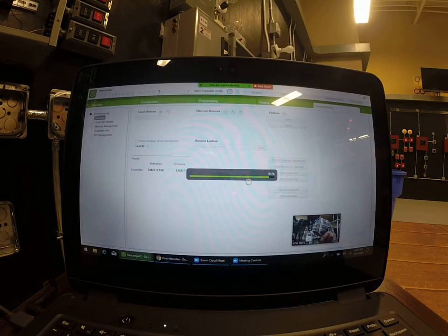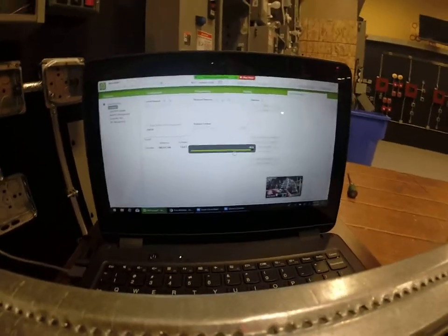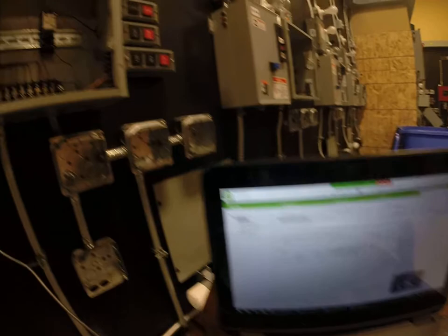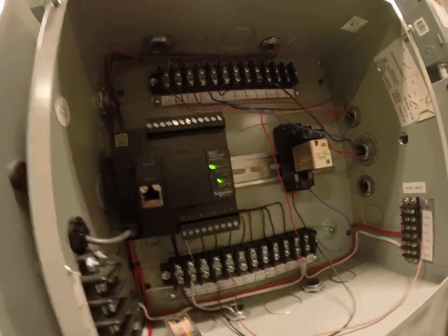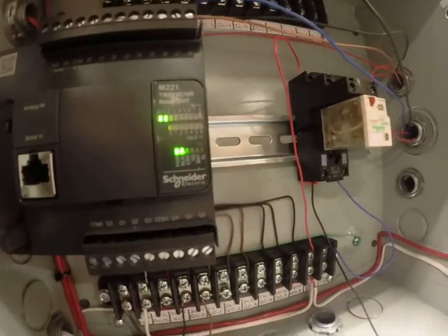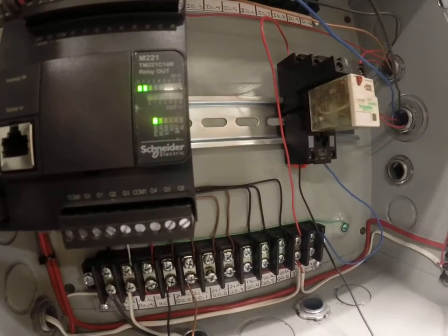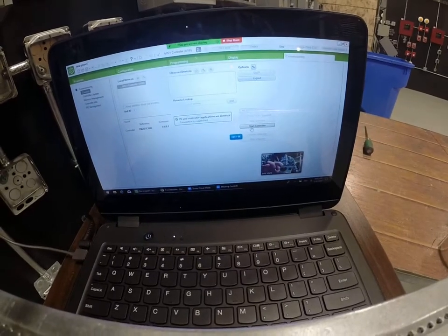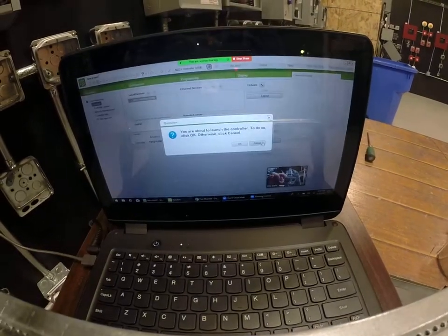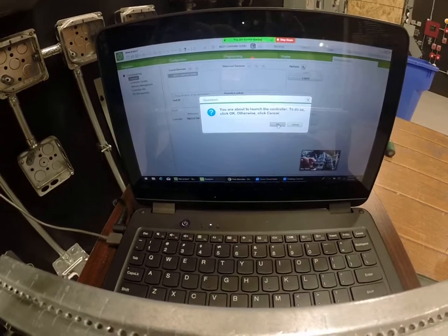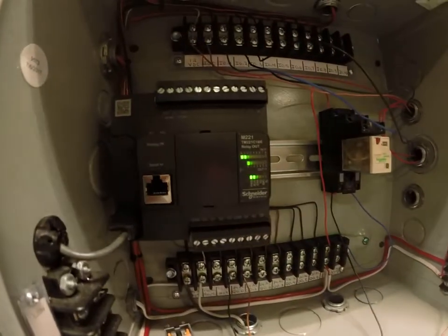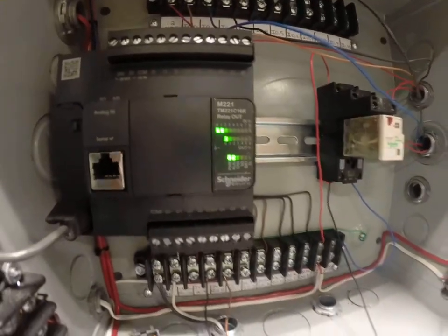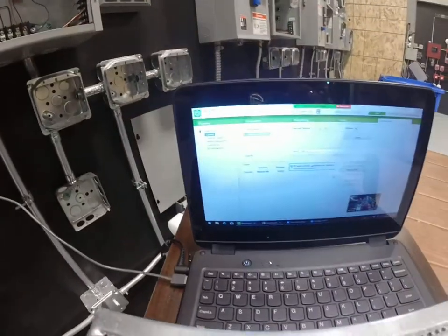And a couple things you're going to see. It's clicking away, waiting. If I come over to my PLC, you'll see that the bottom set of LEDs is blinking. It's because it wants you to hit start controller. So if I come back over here, I look for that icon, start controller. I'm going to launch it. Now I'm going to come back up and I have a solid green light, a solid run light on my PLC, which means it's ready to be actually working.